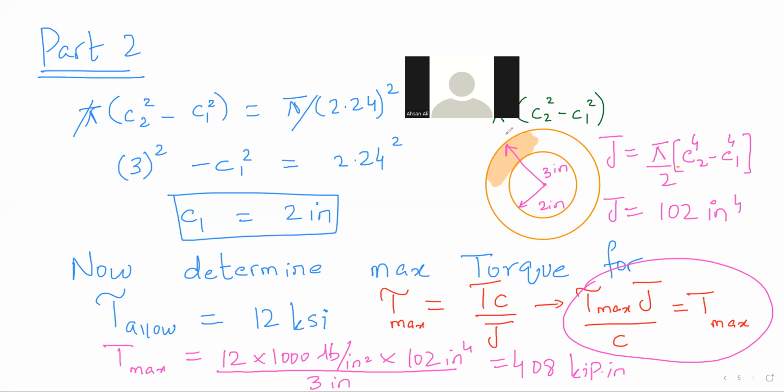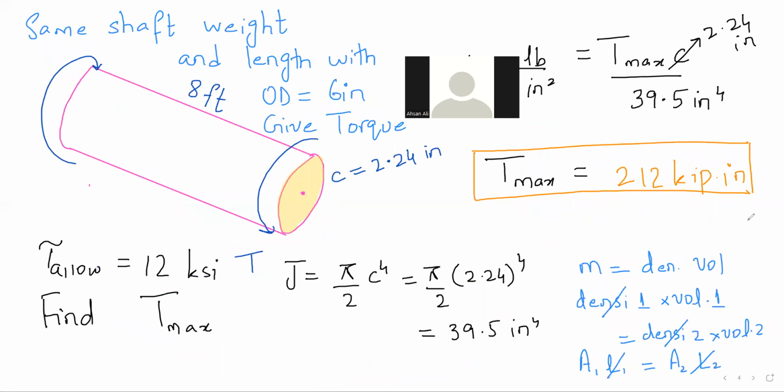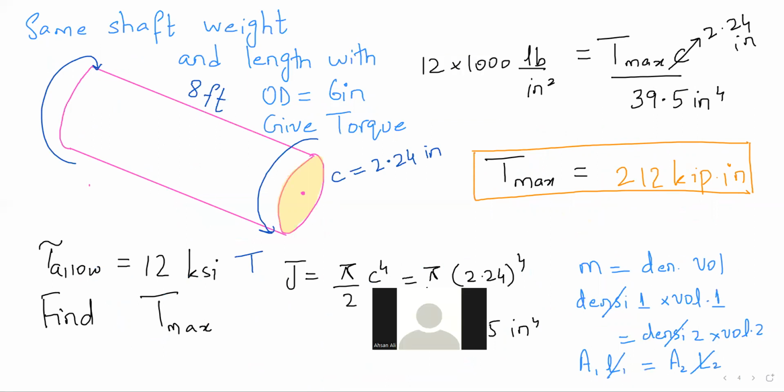No worries. Can you go back to the previous slide? I will. So there is this torque arrow on the front side of the cylinder. It's in the anti-clockwise direction, and on the back side it's in the clockwise direction. How does this make sense? Because if I am holding the left side by my hand, and you are trying to twist it anti-clockwise from that side, the reaction will automatically be clockwise. That's why this is in static equilibrium. So you remove the support, and this time from our hand, even if we put a clock on the other side, that would make sense.